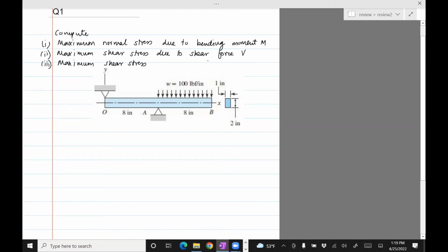Now, when you say maximum shear stress, this means that you need to compute it using the transformation of stresses. So in one plane, the stress would be sigma x, sigma y, tau xy, but there's a plane in which the shear stress is maximum, right? You need to find that. I believe I gave this question in the exam. You said to find it at a particular section, section 10. I see. Okay, but let me just highlight the solution for this one.